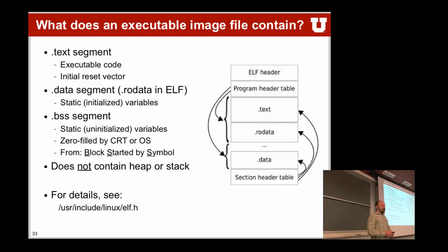The key to this is also that it does not include a heap or a stack, because that's sitting usually in RAM, and you have to make sure that whatever is in the BSS section does not collide with your stack itself.